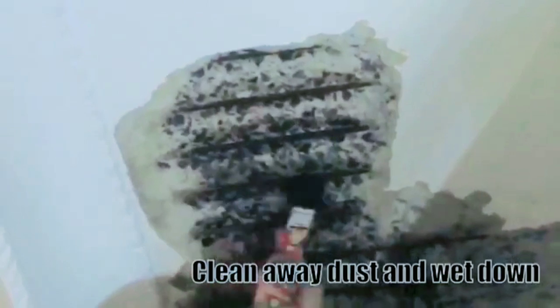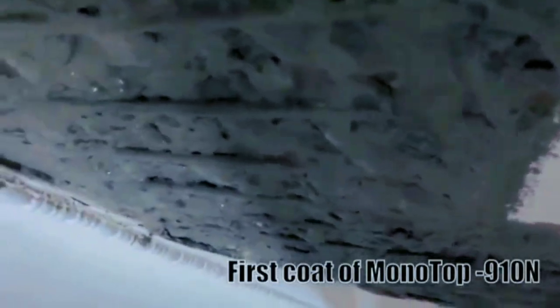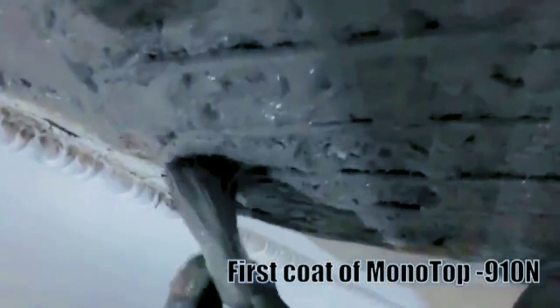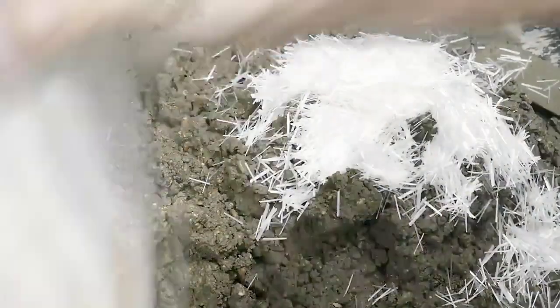It is not enough to just render over the concrete to hide the rusting steel, as the rusting process will just continue underneath, causing further displacement of the concrete and even necessitating replacement of the reinforcing steel altogether. Rather, the cause of the concrete cancer needs to be appropriately identified before a fix can be applied.